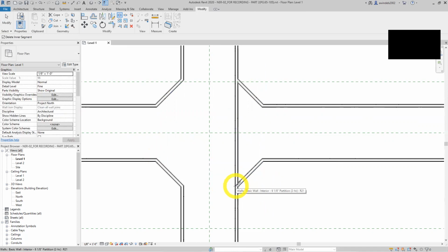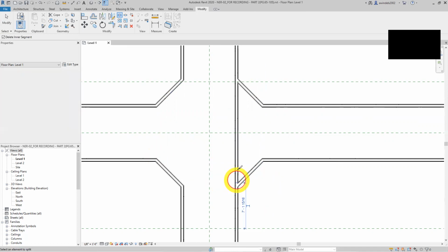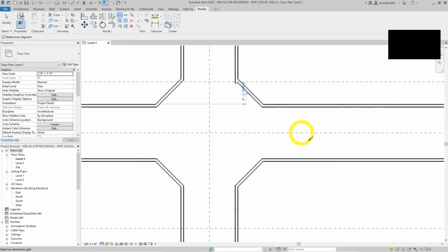And you see how when I hover this, get it kind of in here. Let's try doing it here to here. It leaves a little nub there, right? So Control Z, your friend for undo, or up here. Control Y is redo, or here. You're going to use those a lot. Let's hit Escape, Z one more time. Let's go back to our command, split element, and let's split it. Right, that one looks good.